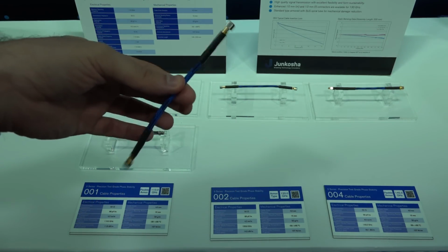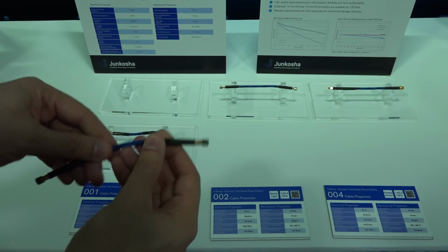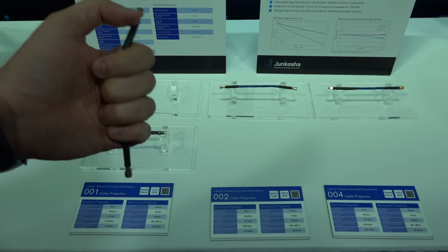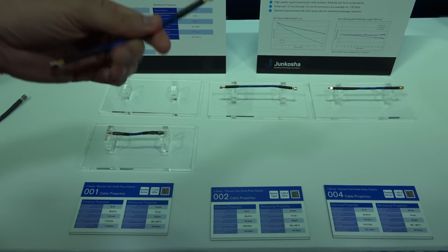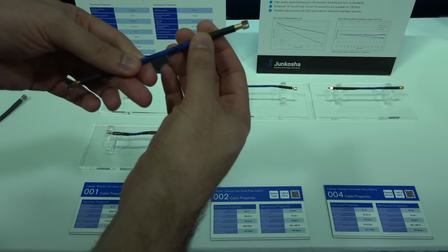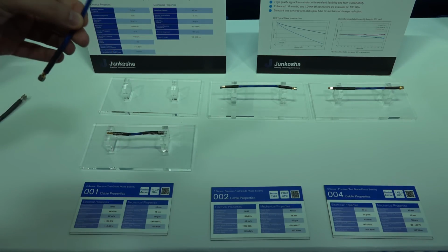I mean, that's crazy. This is a 1 millimeter cable supporting up to 110 gigahertz. Super flexible, which is really helpful nowadays because there are so many interfaces with 1 millimeter. You don't want any strain on these connectors. You want to be able to flex them around and connect them easier without degrading the phase and the magnitude of the insertion loss, which is very, very stable, even though it is so flexible.